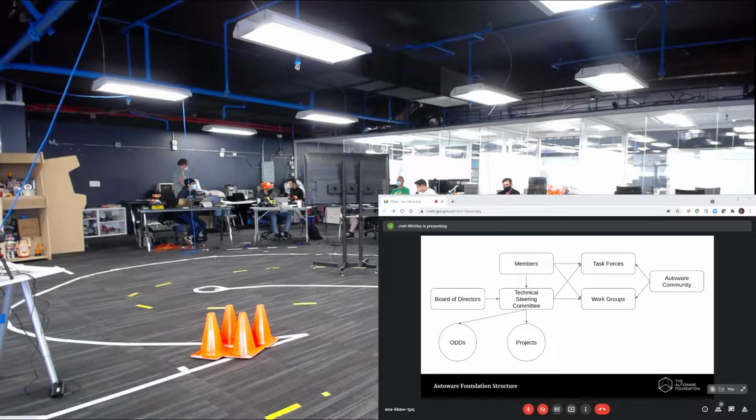So anyway, we do things like trying to make sure that we statically allocate memory every time we start up a process, which is a requirement for AutoSAR and for ISO 26262. All of our types within the Autoware stack are fixed size types, so if we have different definitions for them in the future, it's really easy to change them on different systems. So we try and get close and follow the guidelines for most of that stuff, but not actually get certified.